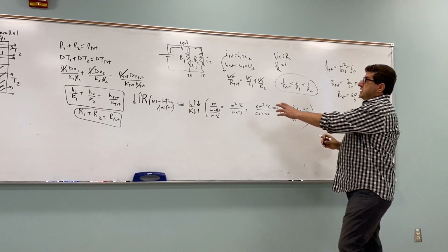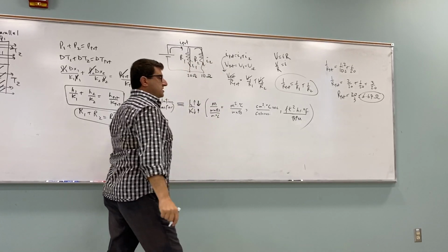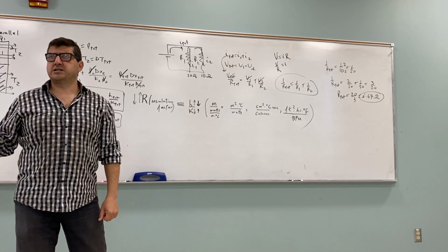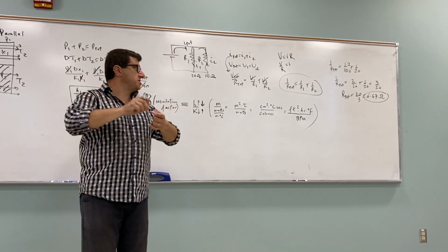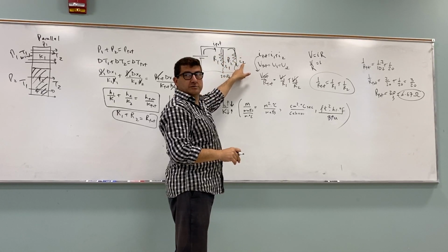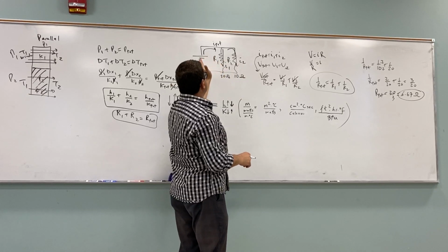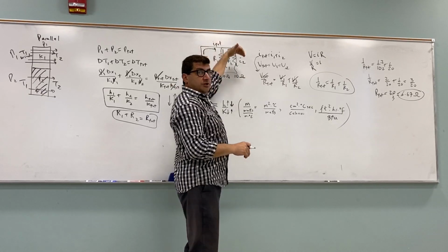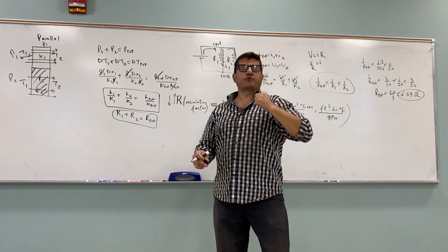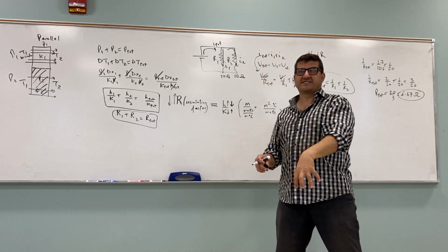Right? So then, if you have a 20 ohm resistor and a 10 ohm resistor, the net resistance in parallel is 6.67 ohms. And the logic behind it is because by giving two resistors in parallel, you have allowed the current two choices to go through. And so it's easier for current to flow through that circuit. You're able to squeeze more current out of that battery, more juice out of that battery, because you have two pathways to take. So you've made the resistance of the circuit less, you see?